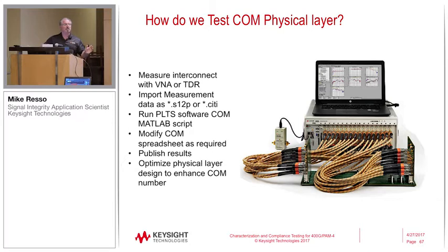Maybe in one space you change the bit rate, 10 gig, 20 gig, 30 gig, up to 100 gig. Then in another space, you run more and more crosstalk, and you can do comparisons. And it's done inside this spreadsheet. So you don't have to be programming, per se. You can leave the MATLAB scripting as is, and just modify the spreadsheet. So it's actually quite convenient.